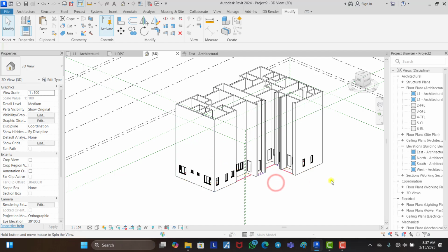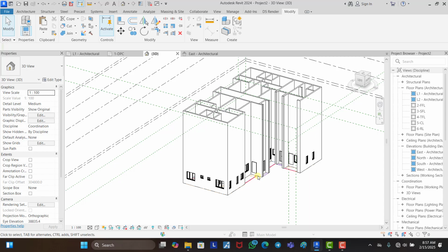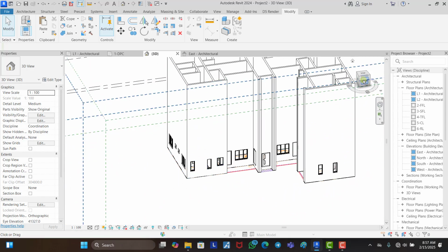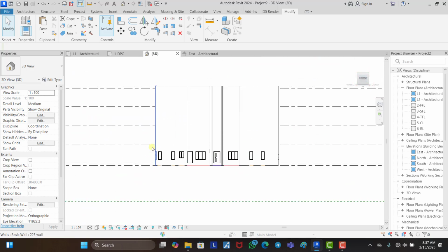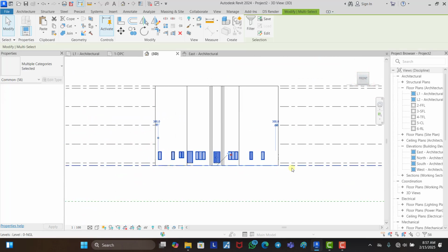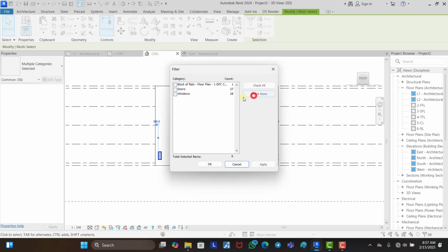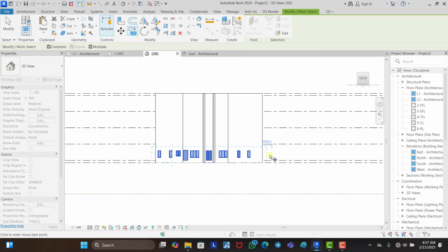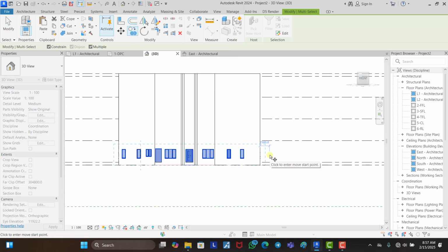All right, good. So the next thing to do now, as we have adjusted the walls, is now to adjust our windows. Good. So we just click on this, select everything, check none, select windows and doors. You click on OK. Good. Then we can click on copy. Now all the windows and doors, the placements are the same thing all the way to the top, so let's just copy it instead of going there and recreating the windows all over again. So we just click on copy.